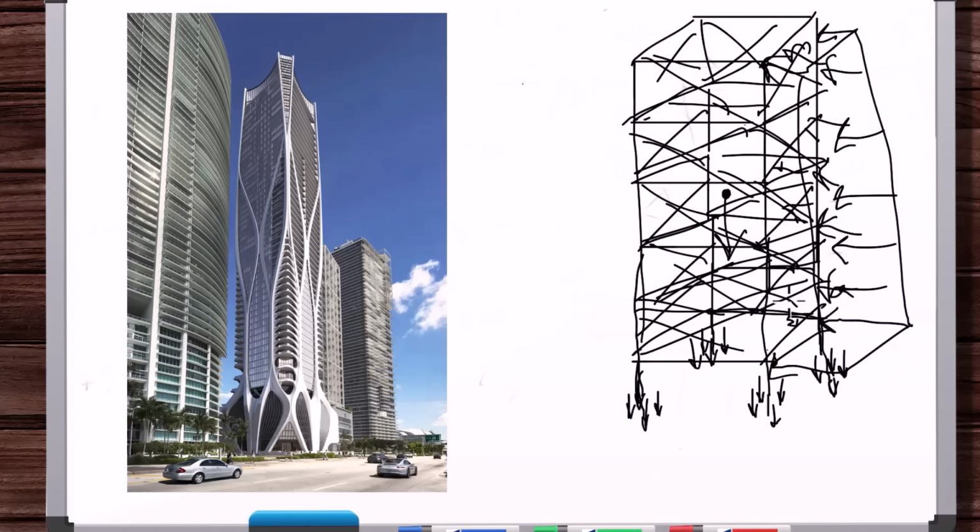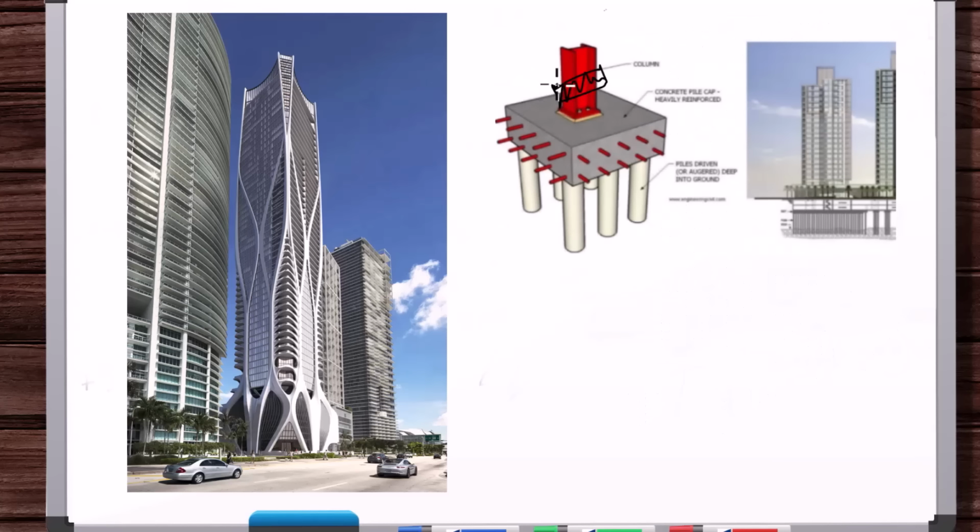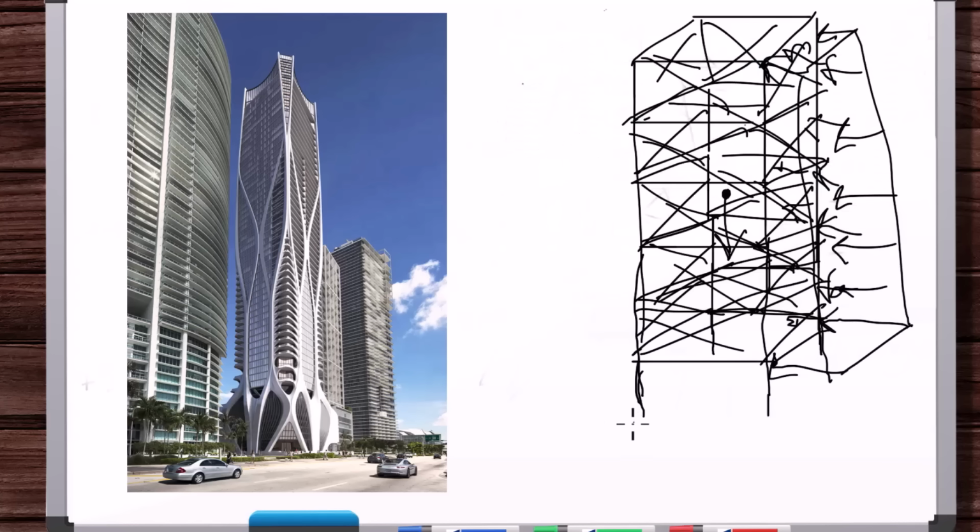It seems like, how could it possibly be that simple? This huge structure with hundreds of beams. It's this enormous skyscraper. This would be the free body diagram for that scenario. If you unbolted the beams at the base like we just showed, that's the only contact points between exposed surfaces and the surroundings. That's it. If we made a cut like this at each of those beams, then at each point, the resistance to motion would be 3 forces and 3 moments.